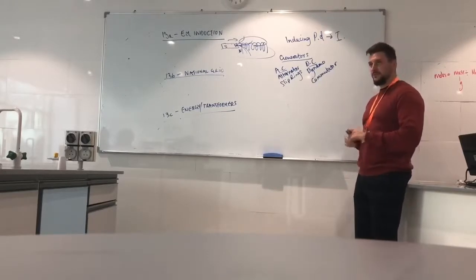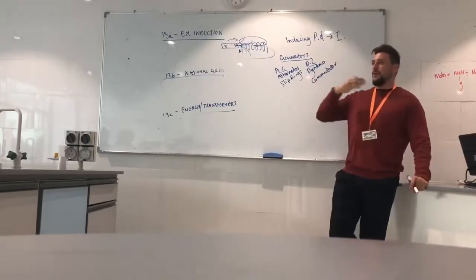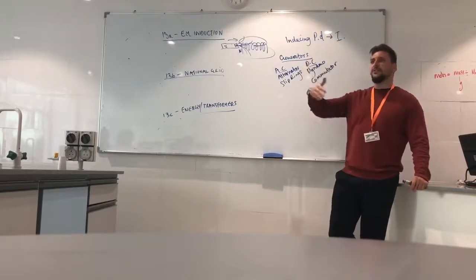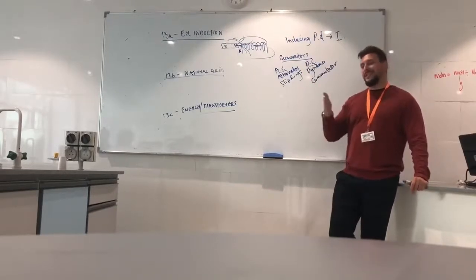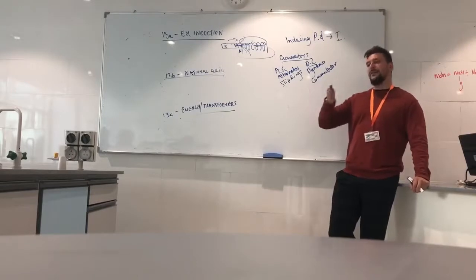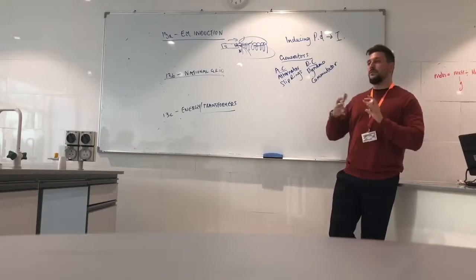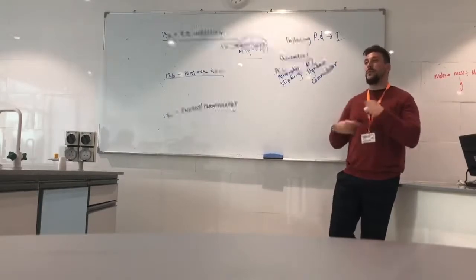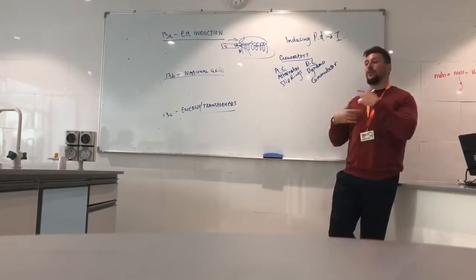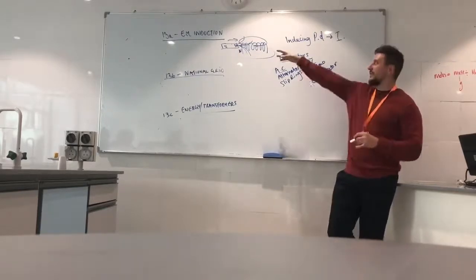Microphone and loudspeakers. Okay? Microphone creates sound. The pressure in the air gets transferred by vibrations to the diaphragm of the microphone. When it hits, the diaphragm is going to vibrate in the same way as the sound in the air outside is vibrating. If the diaphragm is connected to a coil, the coil moves, or pulsates, forwards and backwards around a permanent magnet. In that coil, a potential difference and current is induced. So that is electromagnetic induction.